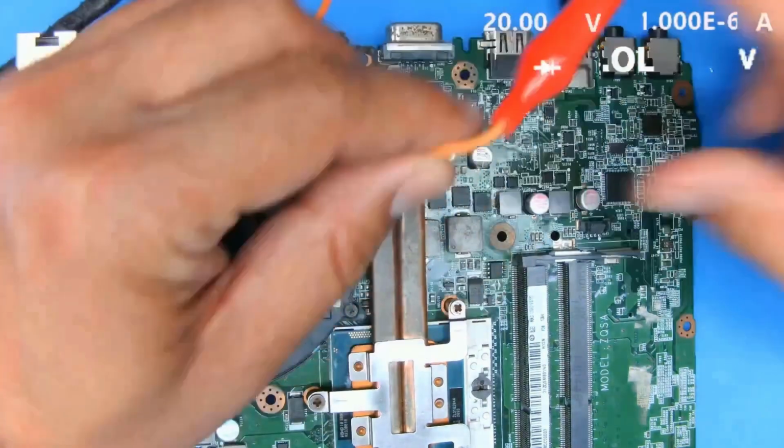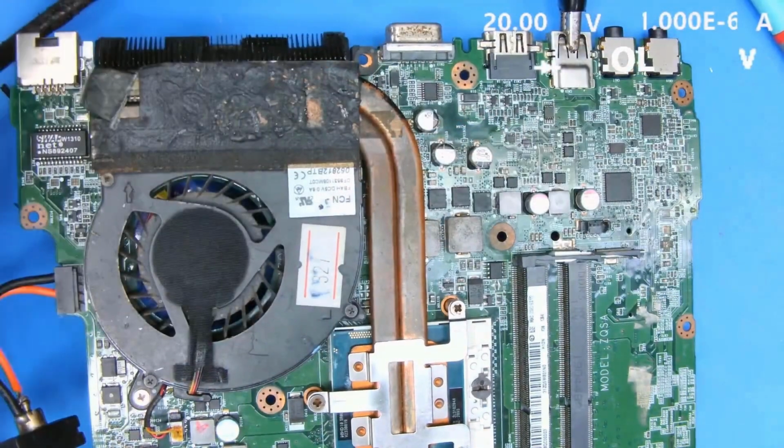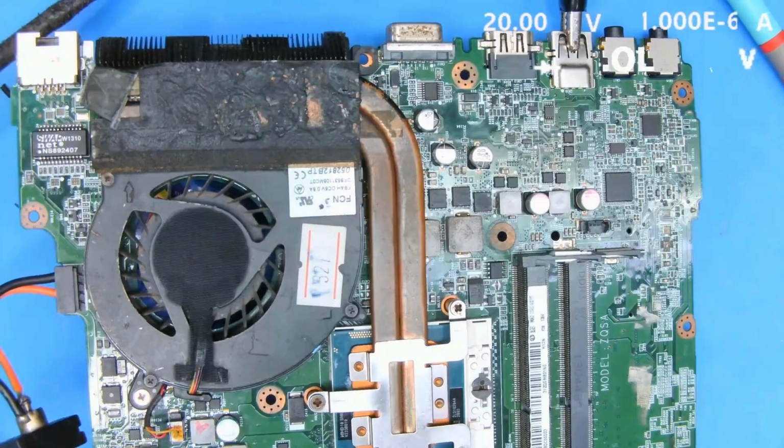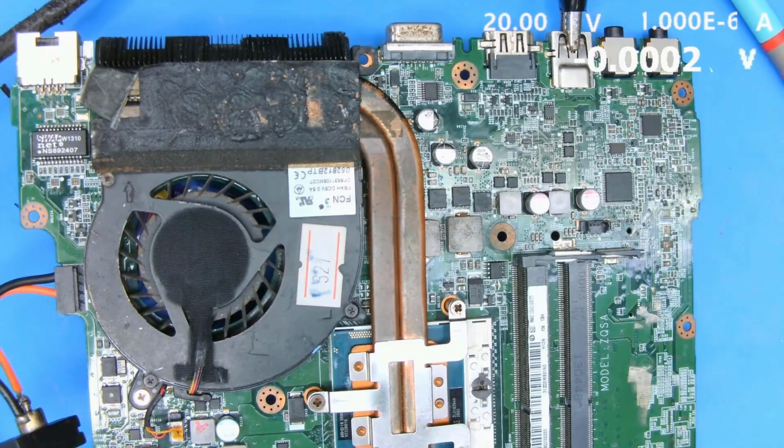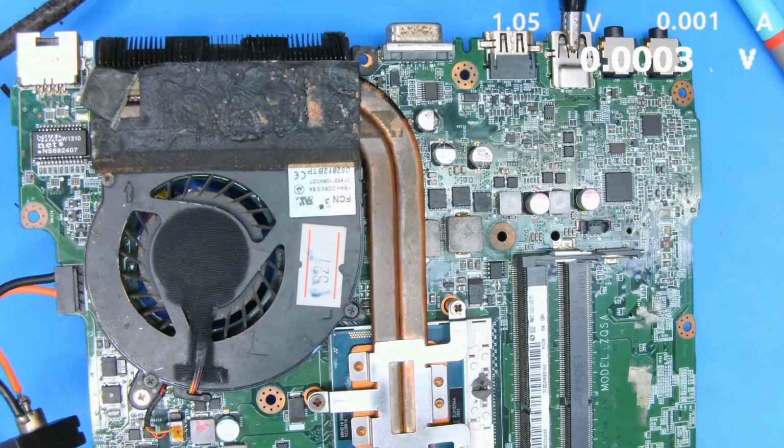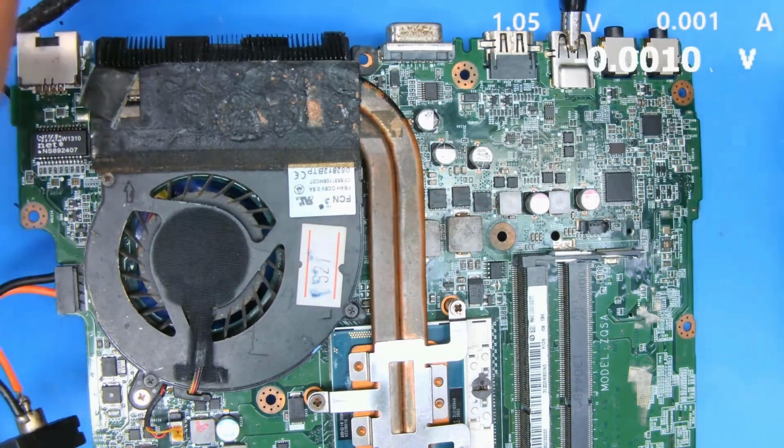Here, we can't inject 19 volts because the voltage is too high. When we're supplying power, we can set our meter to the voltage range first, then adjust the voltage on the power supply. If your power supply has a voltage adjustment knob, turn it down. If it's digital, just press the button to lower the voltage until it's only about 1 volt or 1.2 volts. Either is fine. About 1 volt is enough, or even less than 1 volt, like 0.8 or 0.9, that's fine too. It can be less than 1 volt, or you can set it exactly at 1 volt. Just don't go over that, then connect it.